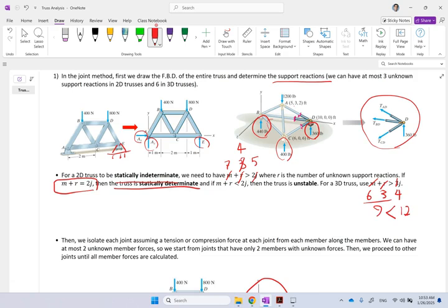That means if you just have it on 3 rollers like that, this is not a stable truss. Why not? Because if the force applied from outside is just vertical, yes, it is going to hold. But if you have a slight force in either the z direction or the x direction, none of the external reactions can stop the truss from moving in the z or x direction.